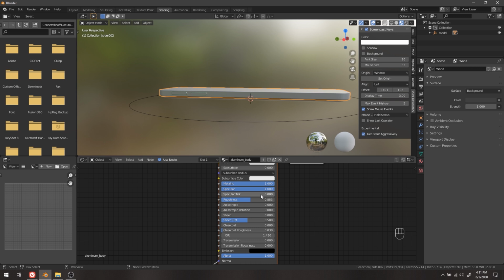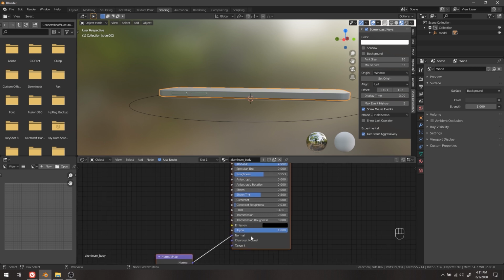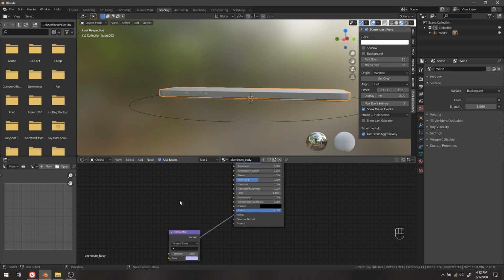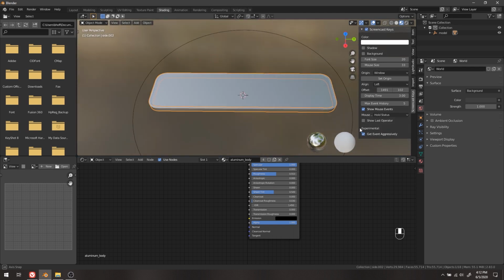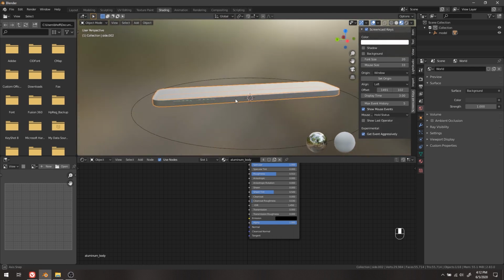And then you have inputs for the bump mapping underneath the normal. And then the rest of it we can get into at a later date, but isn't really necessary for this tutorial. By default, when Blender imports FBXs, they import with this normal map node. You can just press X to delete that. It's not entirely necessary. So right now, we're working on the exterior part of this remote.